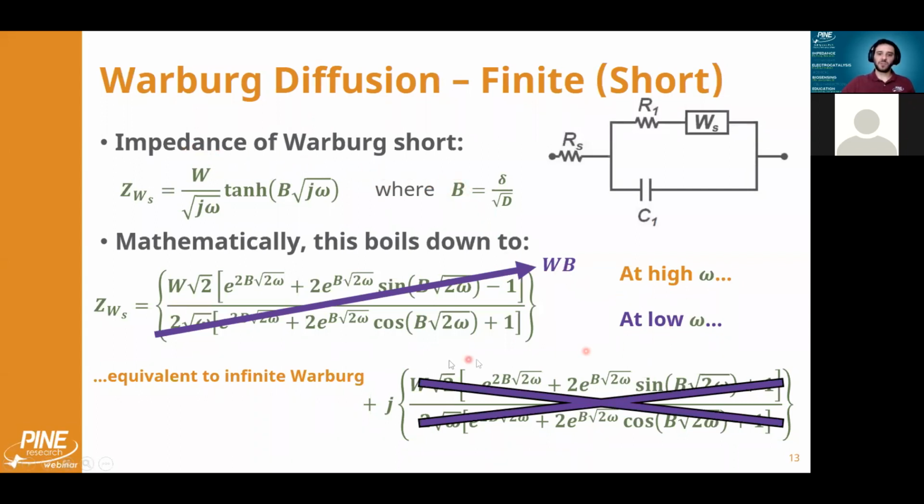So at low frequency, the impedance of a Warburg short becomes a circuit element with 0 imaginary impedance and only real impedance that is a constant and not dependent on frequency. Well, if you recall, what I just described is a resistor. That is to say, an element which has only a real impedance that is equivalent to a constant.